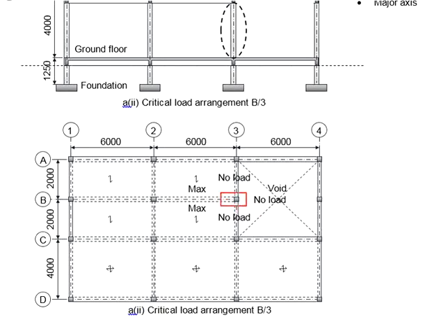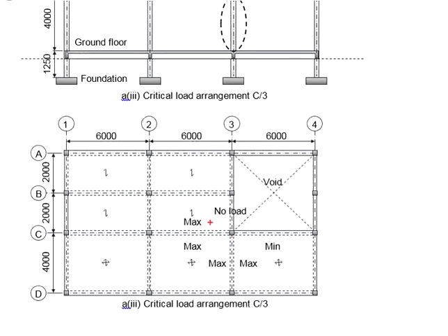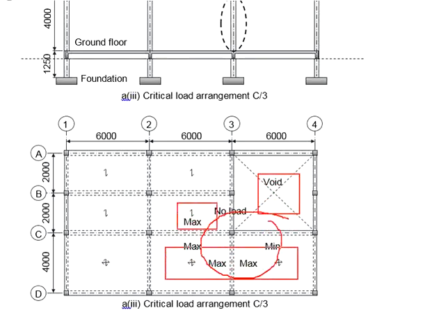The column arrangement will be something like this: 300 here and 150. The bending is in these directions. Therefore, it is only uniaxial bending towards the major axis. Next, we look at column C3. Surrounding the columns, we have the void, one-way slab, and two-way slabs.